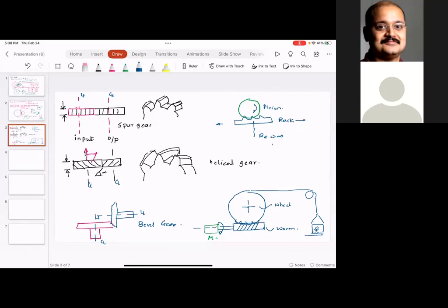So that's why usually you have oil coolers in engines, and those oil coolers sit somewhere where the radiator fluid is flowing to the engine, basically the water jacket. So those are the more important applications of lubrication. And what we will do is, sometimes in these gear designs, one of the gear design exercises is not to design the gear, but to design the housing.